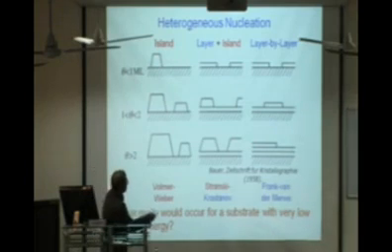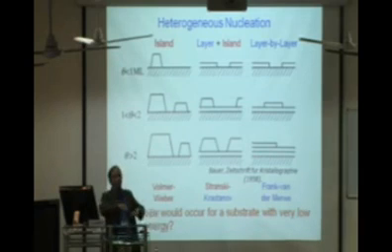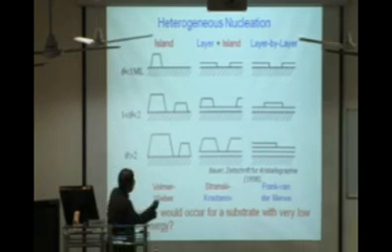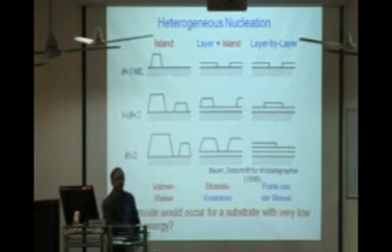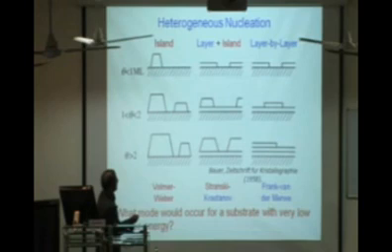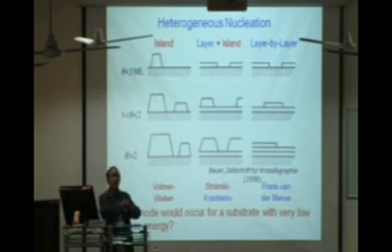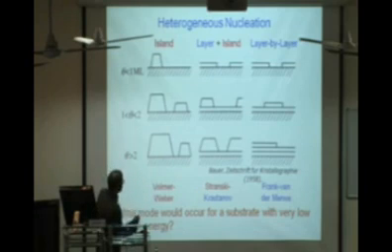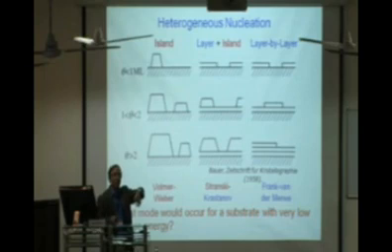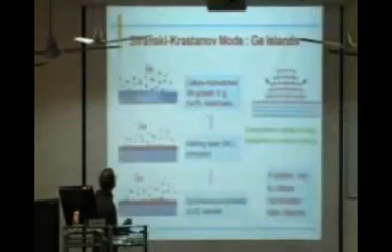In some cases, it goes layer by layer, just like water on a glass plate. So it's a perfectly two-dimensional growth. This is typically used for electronic devices or making the epitaxial layer. But there is something in between. If you grow a lattice-mismatched semiconductor thin film on a substrate, initially it spreads. But since there is lattice mismatch, strain builds up, and this strain changes the growth mode from 2 dimensions to 3 dimensions. So they make so-called quantum dots this way. In fact, I have shown almost the same thing here.